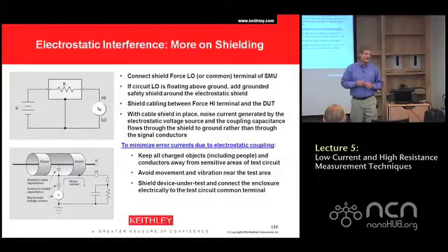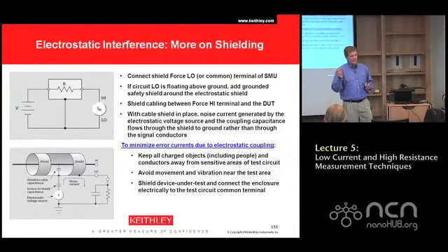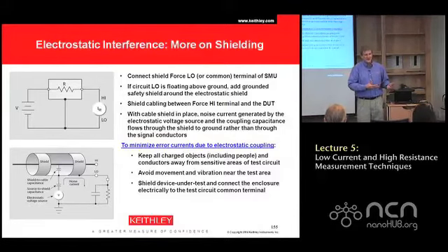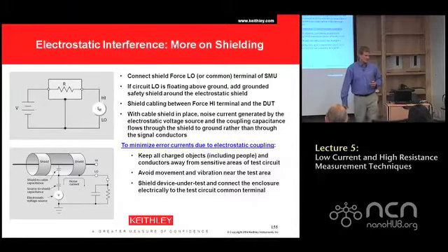You mentioned you're from India. I was in India a couple of years ago, and I was surprised at the variety of probe stations that you find in the different research institutes there. Things that have been around for a number of years, things that have been cobbled together from whatever pieces happen to be available. We saw one case where there was a piece of wire stuck in the back in the triax connector, run over to the probe station. A plain piece of wire, okay? There's not a chance that that thing could ever make a good measurement. But if somebody doesn't understand the basics of measurements like we're teaching today, and if that's all they have, they're going to try and hook it up and try and get the measurement, and then perhaps not understand why it doesn't work.